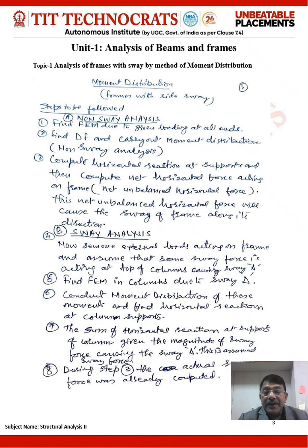Then, assuming some arbitrary value of sway force, say P, find out the moments in the columns due to this applied sway force P at the top of the column. At this stage, you have to ignore all the loading acting upon the column.